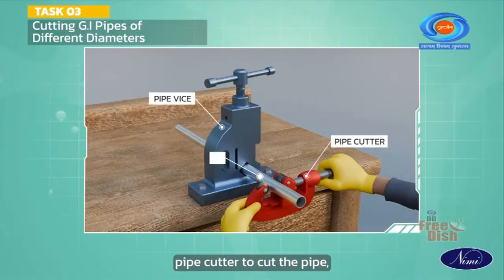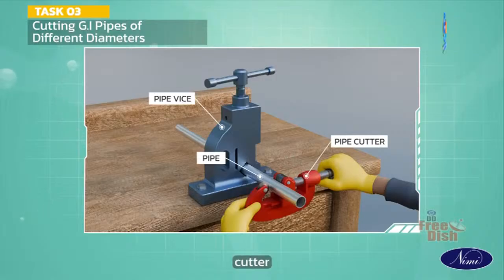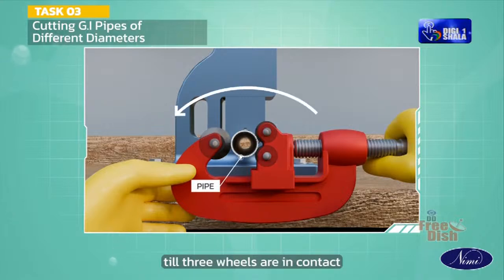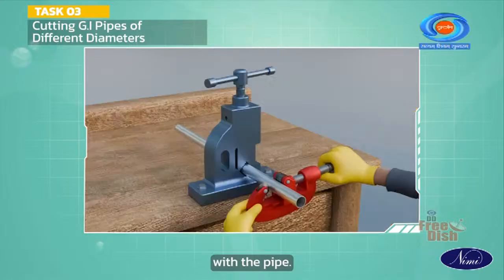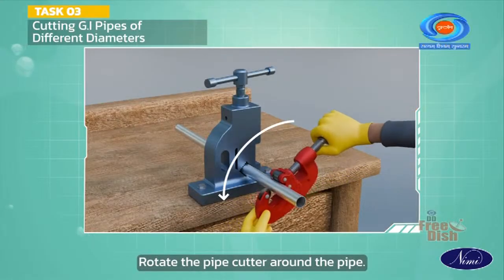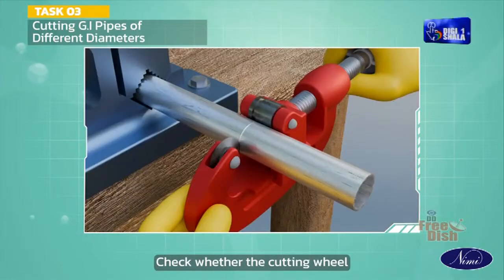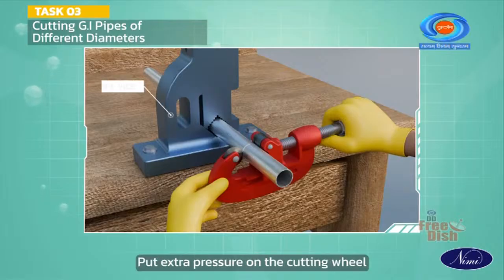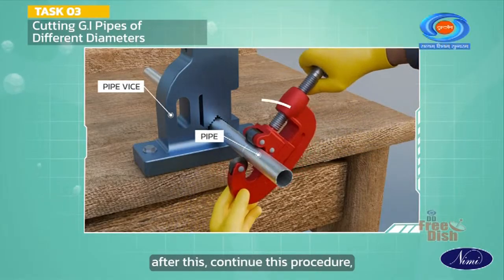If using a pipe cutter to cut the pipe, then fix the pipe in the pipe cutter. Rotate the handle to adjust the cutter till 3 wheels are in contact with the pipe. Rotate the pipe cutter around the pipe. Check whether the cutting wheel is sitting exactly on the scribed line after 1 or 2 turns. Put extra pressure on the cutting wheel after this.